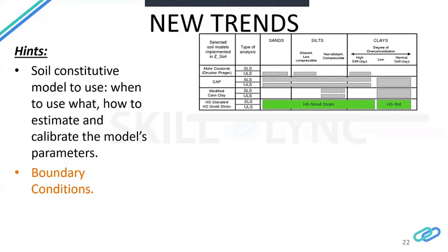However, there are certain geotechnical challenges where you cannot use this, at least not alone. If you have liquefaction, or creep, or cyclic loads, you have to consider another constitutive model. But generally, in foundation system problems, especially on sand, clay, or silt, you can use the hardening soil model or the hardening soil with small strain stiffness.